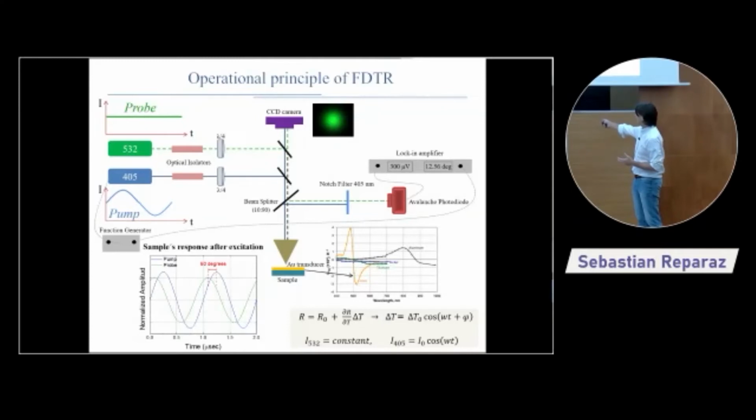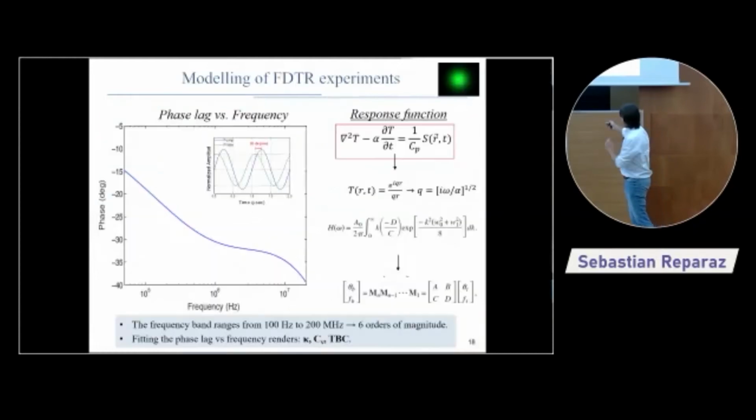This that is written here in time scale, it's a time offset that you can translate very easily to degrees when you're measuring by using a lock-in amplifier or thinking in vectors, okay? And it's actually this quantity, the one that will help you to obtain the thermal diffusivity of the sample, okay? So going straight for that, what you do is to measure this phase lag.